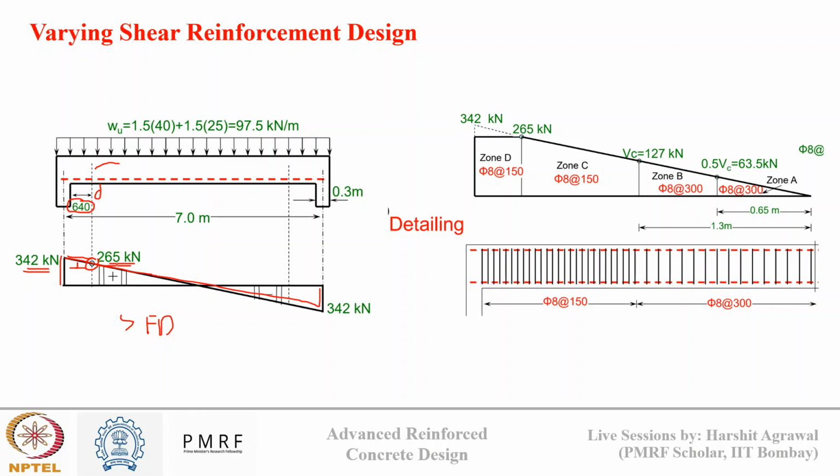For this distance d, this is my Vu. For this I will calculate tau v and design the shear reinforcement. However, we see that as we go away from the support, the shear force decreases.